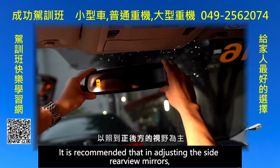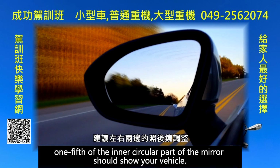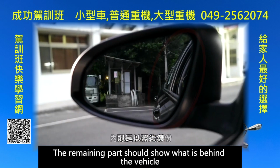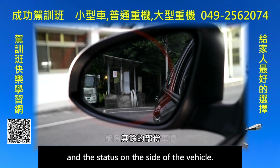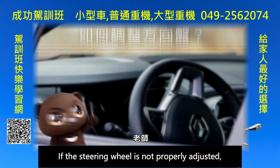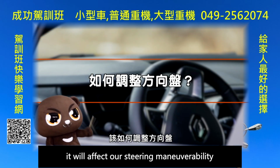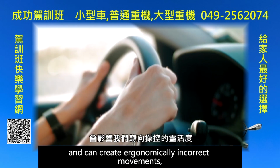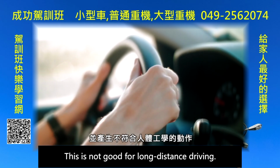It is recommended that in adjusting the side rearview mirrors, 1/5 of the inner circular part of the mirror should show your vehicle. The remaining part should show what is behind the vehicle and the status on the side of the vehicle. Teacher, I have one last question. How should the steering wheel be adjusted? If the steering wheel is not properly adjusted, it will affect our steering maneuverability and can create ergonomically incorrect movements, leading to hand, back, and shoulder soreness. This is not good for long-distance driving.